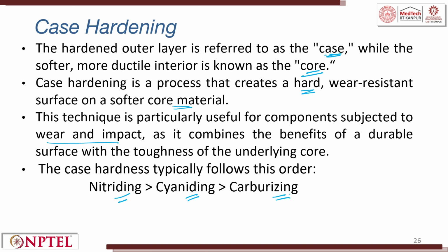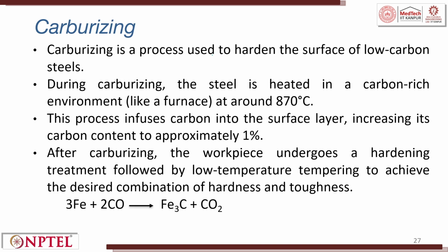Carburizing. Carburizing is a process used to harden the surface of low carbon steel. During carburizing, the steel is heated in a carbon rich environment at around 870 degrees Celsius. Carburizing is nothing but what I told you, a blacksmith. This process infuses carbon into the surface layer, increasing its carbon content to approximately 1%.